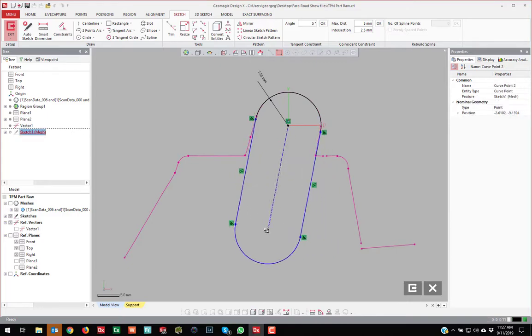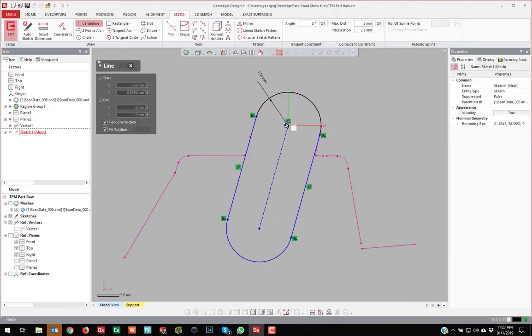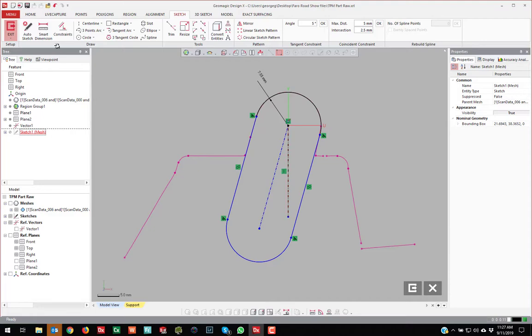So that way when I drag it and change the angle, I can even apply another center line straight down with a vertical constraint to it. And then I can select those two lines and even apply, let's make this 15.5. So I can dimension everything about this slot here and create a nice, accurate sketch of exactly what it should be.